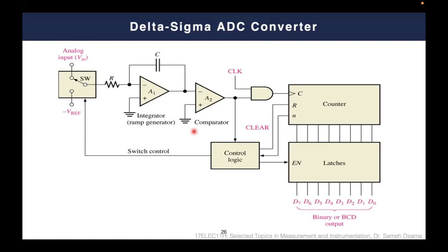In the coming lecture, we are going more into electronics. We are going to demonstrate more about what is inside these structures. So for example, in this lecture we demonstrated the comparator as a triangle. This comparator has a positive terminal, a negative terminal, and an output. If V plus is greater than V minus, the output is high. If V plus is smaller than V minus, the output is low. This is simply what we did. But what is the electronics inside this comparator?